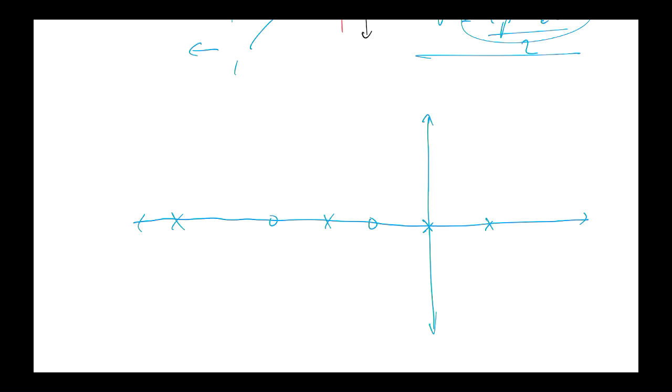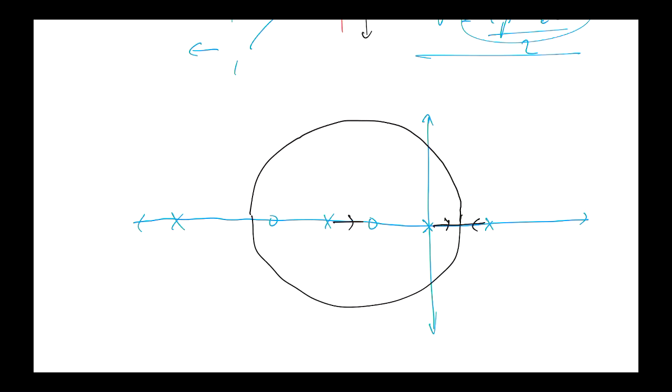And we drew that the root locus plot would look something like this. This guy would go there. And then we had this guy going around, right? Coming around like this. That goes that way, that goes that way, that goes that way. When they meet here, they split apart, and one goes towards that 0. One goes this way, but then it meets this guy, and then they split apart and go to zeros at infinity along 2 asymptotes, right?